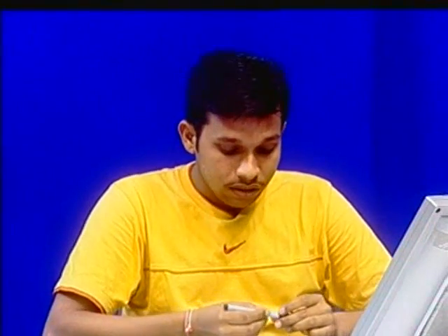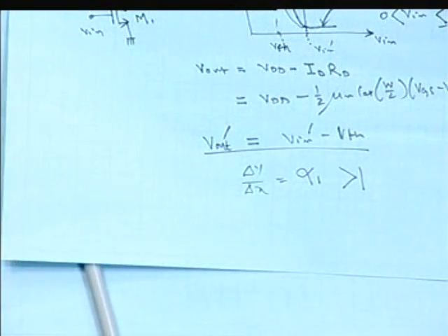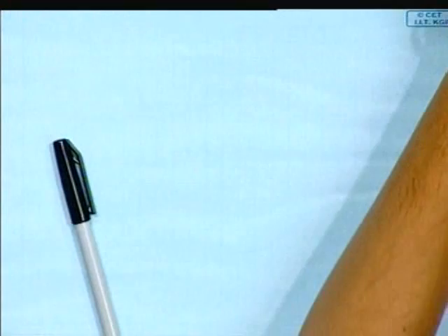Firstly, we have to define the AC ground whenever we analyze that particular MOS, or whatever amplifying system, in a small signal model. AC ground is a node where there is no AC variation. We apply the input voltage superimposed on the DC operating point, which can be anywhere in the saturation region; in this saturation region we fix our bias point and superimpose an AC signal.